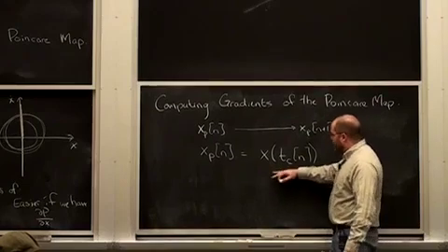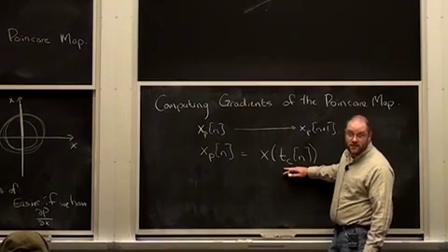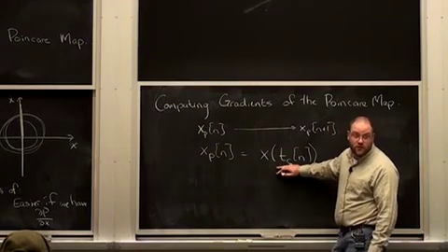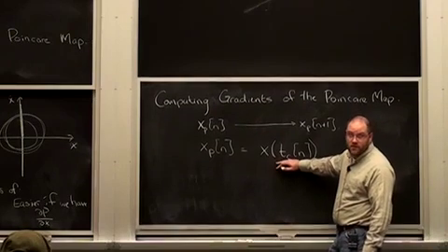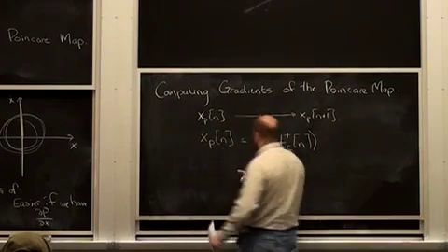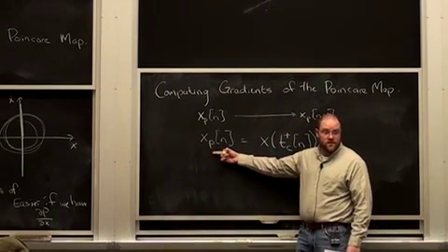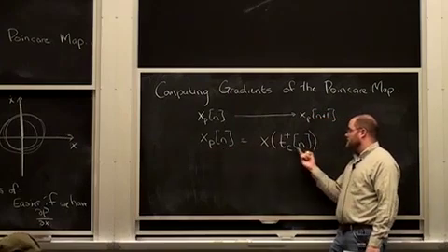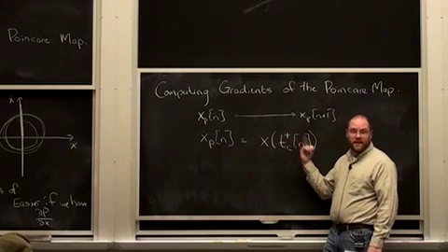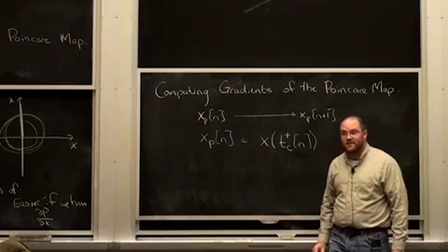In the walking case, because the collision has some dynamics, we want to be explicit about whether it's before or after those dynamics, before or after the collision. So I'm going to call our discrete time state of our system the state immediately after I process that collision dynamic. So I'm going to put a plus there. Minus would be just before the collision. They're both at the same time, but there's an instantaneous dynamics.